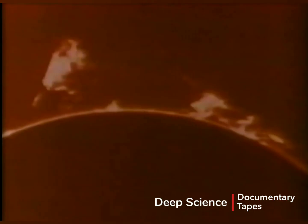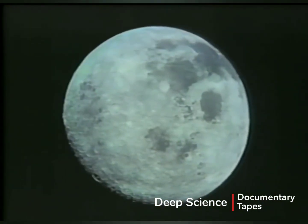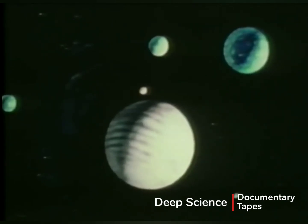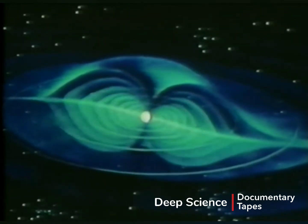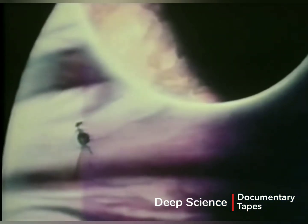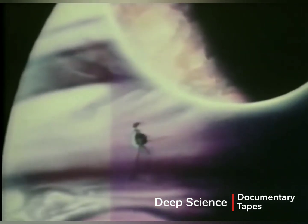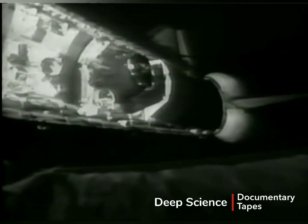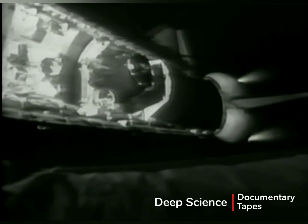Other perturbing forces are the gravitational pull of the Sun, the Moon, and planets, and solar winds, which are charged streams of protons and electrons that heat the Earth's atmosphere and increase atmospheric drag. In most cases, perturbing forces can be compensated for in the spacecraft and orbit design and present no major problems. If the forces disturb the orbit too much, thrusters can be fired to re-establish its desired orbital orientation or altitude.